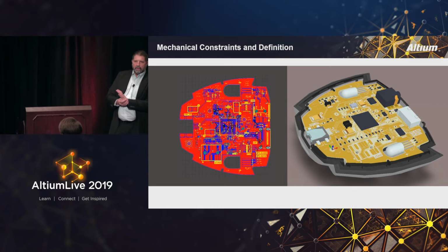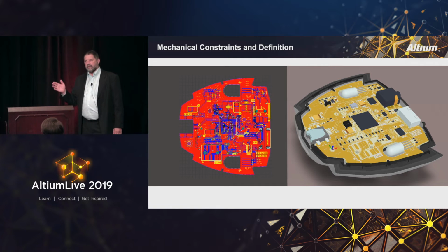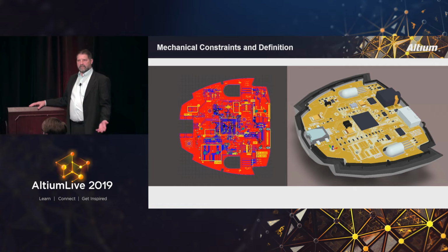And then also, if the mechanical designer is giving you a board outline, you want to have where connectors are located, and connector orientation and connector side. And if there are parts on both sides, they should be giving you both sides. You should be getting 2 DXF files so that you know exactly where things are supposed to be, because that mechanical engineer has planned all his harnesses and other connections to the board, and you have to get that right.